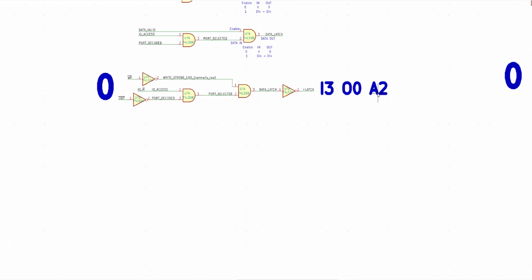Now eventually we're going to need to be combining all of these glue gates into packages. So it'll be useful to see the different variations of the same functional logic, but using the various gates. So my next step is to just start distributing and demorganizing things to swap ANDs and ORs, combining signals, and adding or eliminating inverters. By demorganizing, I mean applying De Morgan's theorem and inverting the inputs and the outputs to allow the gate to be flipped between the AND gate and the OR gate.